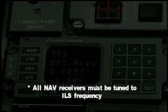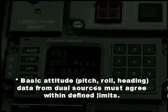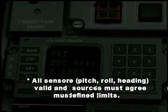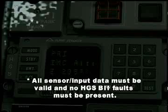All nav receivers must be tuned to ILS frequency. Basic attitude, pitch, roll, and heading data from dual sources must agree within defined limits. All sensor input data must be valid, and no HGS built-in test faults must be present.